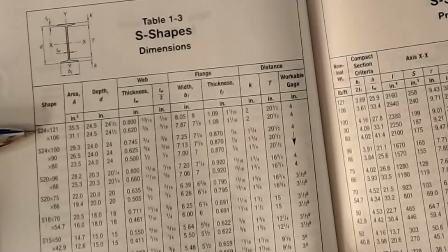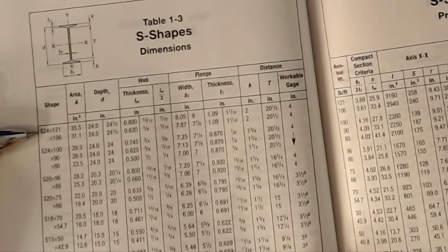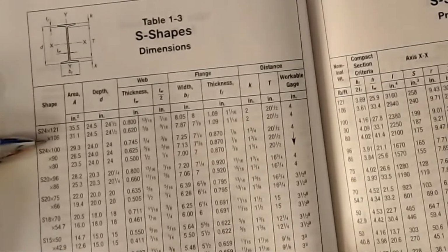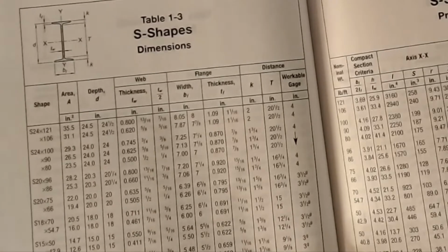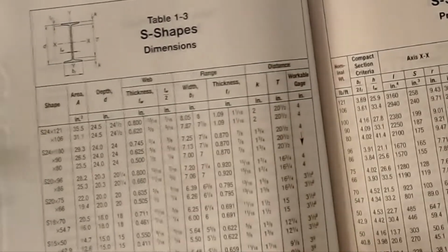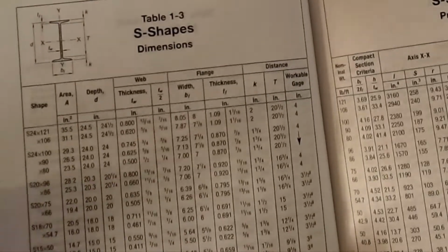Every steel member that's fabricated in the U.S., somewhere on it has a stamp that will tell you what this shape is. For my students, if you go look in KC254, the column that's exposed there, you'll actually see a W8 by, and then its designation is on it. You can see it if you're curious and want to see what that looks like. There are different ways that different companies market. I just know that happens to be the one at our school. But again, everything else is the same.